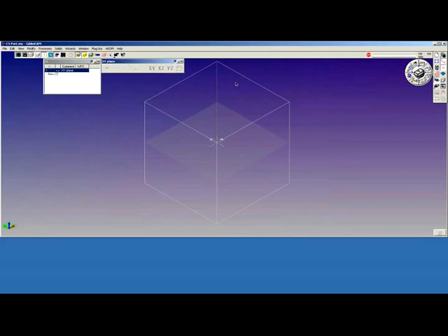and placement. The CS dialog window is accessed by clicking on the second tile down on the right to open and activate the window. Or when you want to select coordinate systems, you can click and hold, and you get a pull down to the left of the button that allows you to select and create coordinate systems. For now, we're just going to activate the window and leave it open so we can see what we're doing.